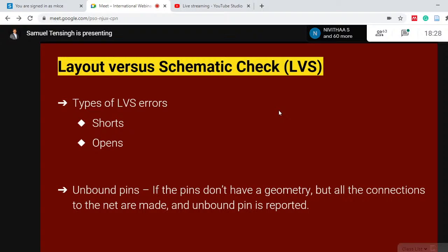So it is better for you to open your post route database, and you always fix your shorts in Innovus. As far as you clear up your physical violations in Innovus, then you do these checks, because these checks are not being done by Innovus. These checks are being done by either Calibre or some other tool. Calibre is from Mentor Graphics.